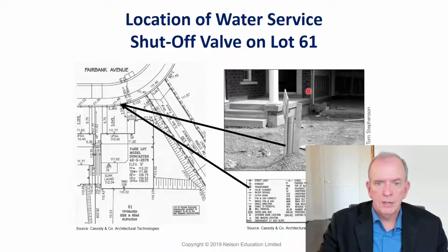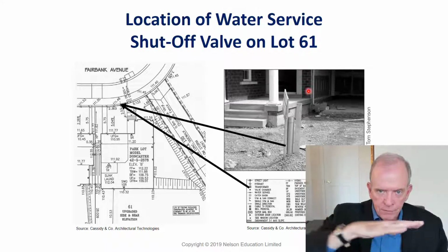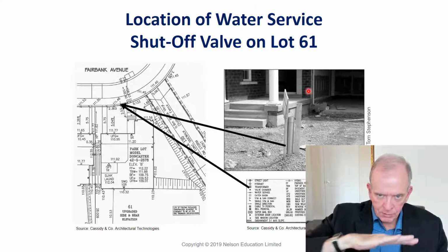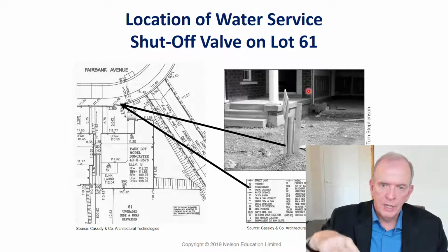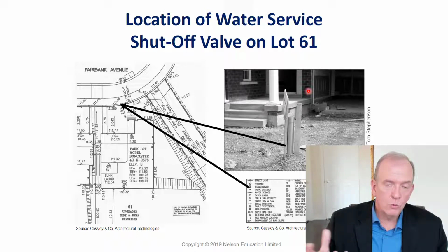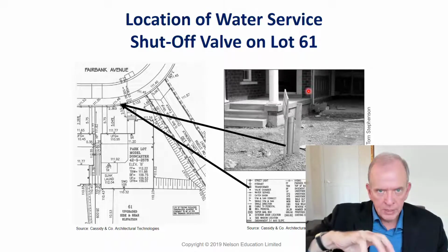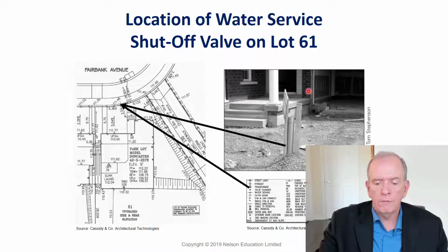So it's going to be right there, in the driveway. There'll be a valve, then it'll be asphalted around it, and it'll come out flush with the driveway. That's where you can turn on or shut off the water to the house. So say you had a flood inside and the water won't shut off, call the municipality, they'll come and shut that off. So that's where that connection point is.